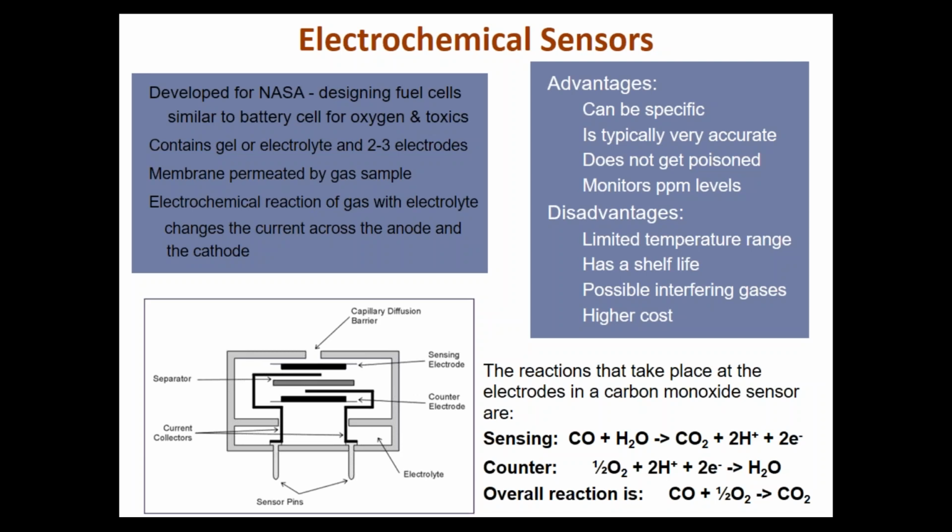Solid state sensors pretty much see a whole slew of different chemicals and vapors, where electrochemical cells have been focused on one or two specific chemicals or groups, such as sulfurs like hydrogen sulfide and the sulfur group.